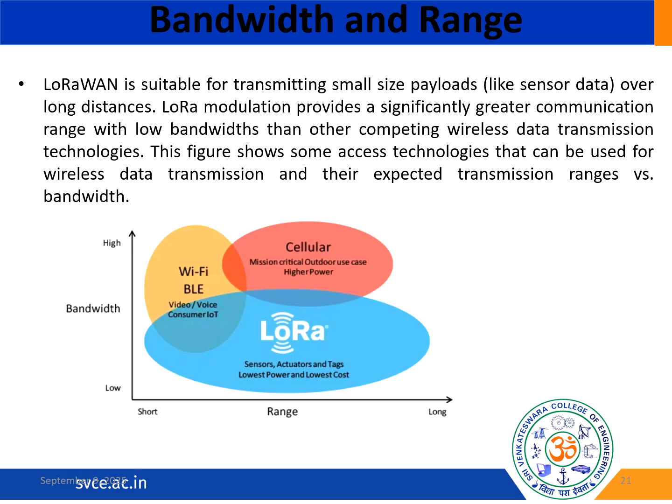Other than that, a LoRa end device can be located if at least three gateways pick up its signals. And considering the LoRaWAN network servers, which are considered to be high capacity, they handle millions of messages from thousands of gateways. So when you compare with other networks, LoRaWAN has high capacity.